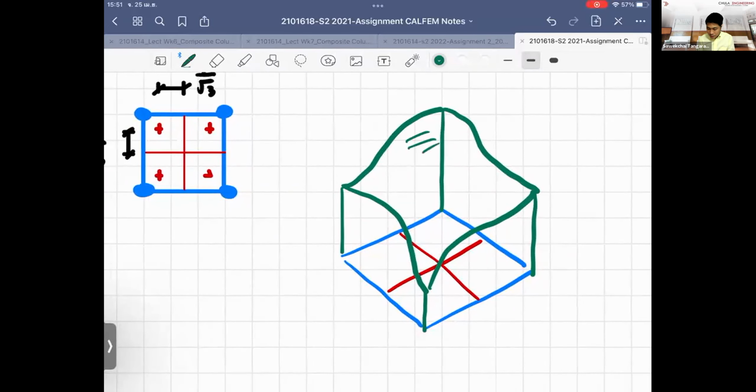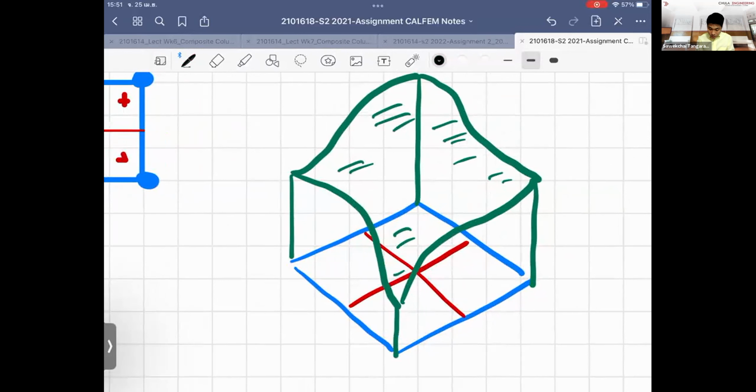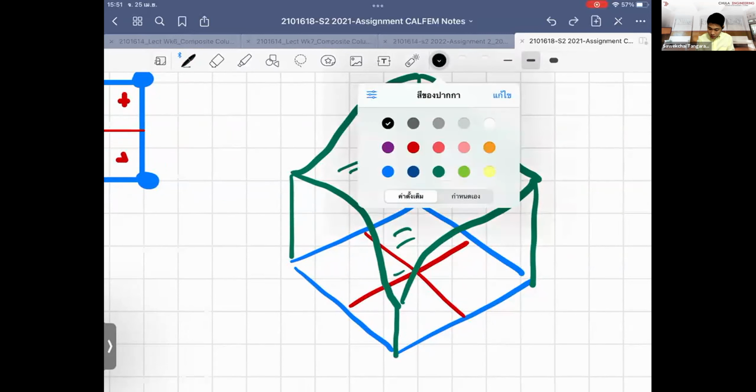This might be the surface of the distribution of the stress. But when we use the Gauss integration rules, what is happening? We see the stress surface, and if you use the displacement fields, this is the approximation of the field of the displacement at the Gauss point. But this is saying that we capture the information of the stress at the Gauss point.